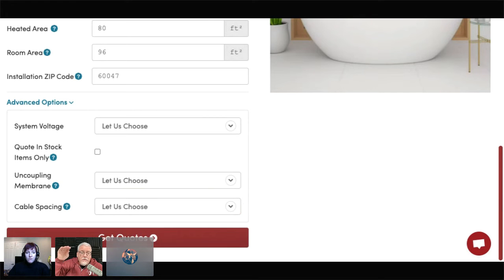The bathroom on the second floor is going to start at 71 or 72 degrees. The floor downstairs over the unheated area in the Midwest could be 30 degrees or could be 45 degrees. So there's a big difference there. You want a lot fewer watts per square foot upstairs over a heated area than you want down on the ground floor, which is on a slab or an unheated area. You want more watts per square foot there. You want the cables closer together. You want more heat downstairs on that cold surface than you need upstairs.